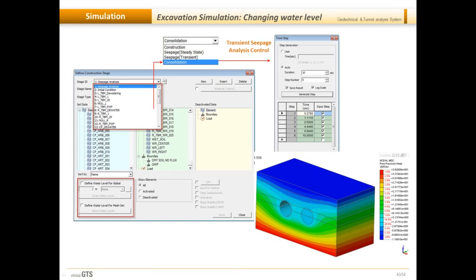And recently there have been a couple of cases where the tunnels have collapsed under these kinds of effects, or have shown increased deformations that have rendered them unsafe for use until further repair. So long-term effects are equally important if you are dealing with soil strata that have clay or unconsolidated layers.